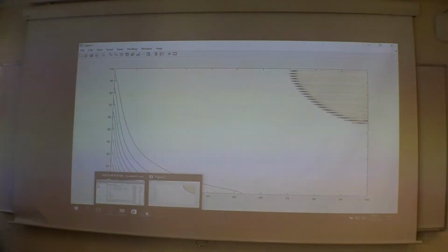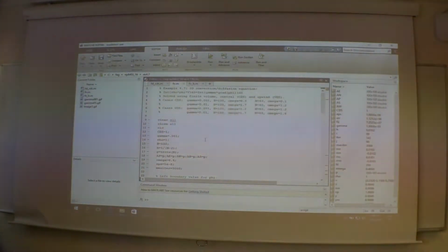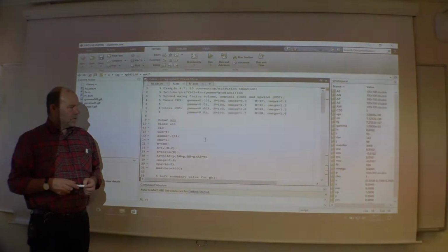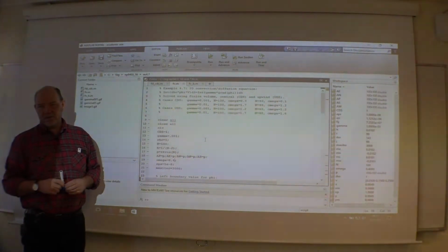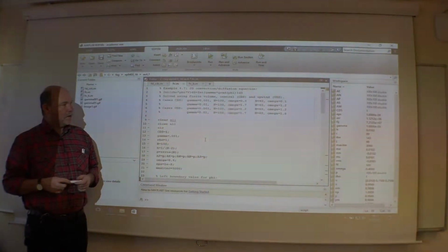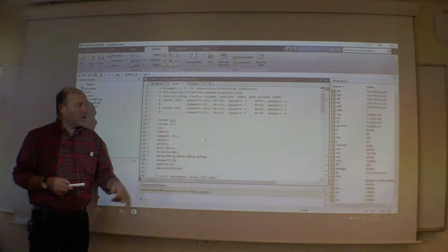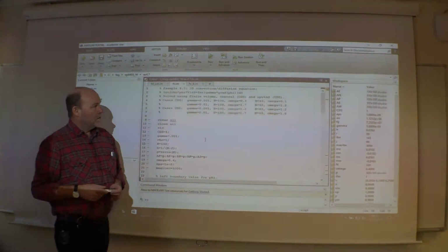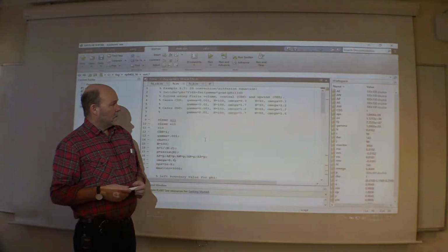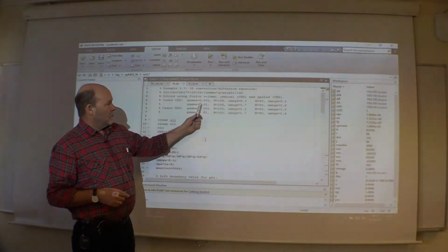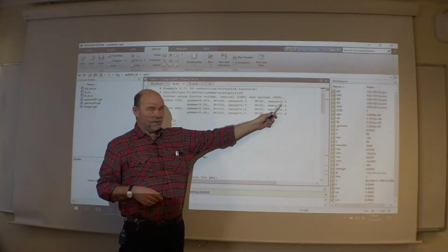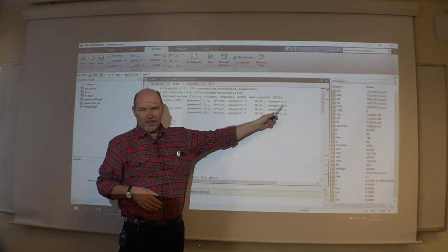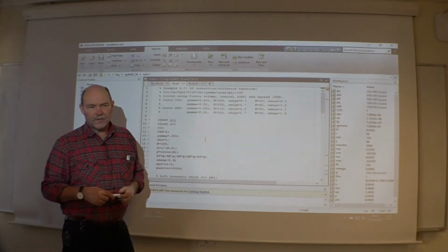So to make a steady state solution, you have to be very careful. You could have solved the equation system here using a direct method, but I think you might be in trouble using direct methods. I think it's so jumpy that it can easily explode. So using an under-relaxation, yes, that is quite more like it. Using fewer points will cost you even more. Then you really have to use an under-relaxation, only 10% adjustments at every iteration. Strange.